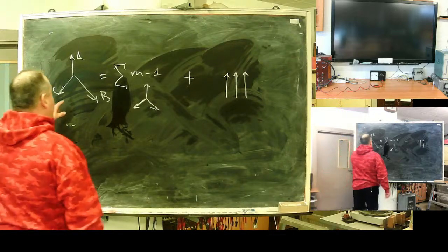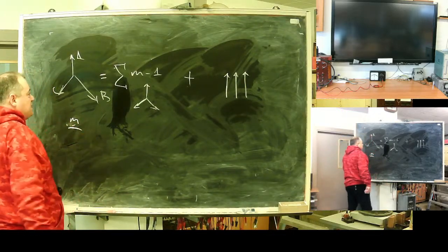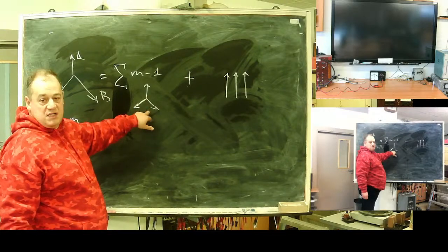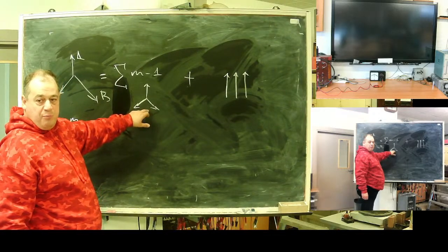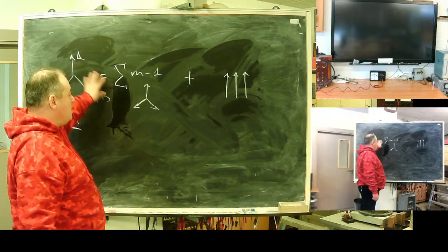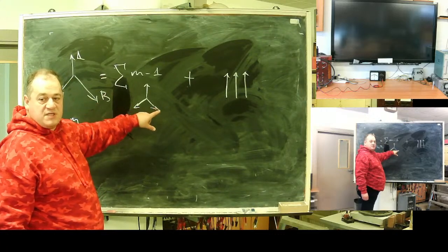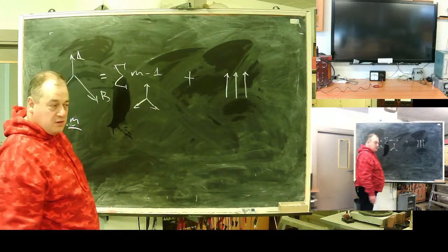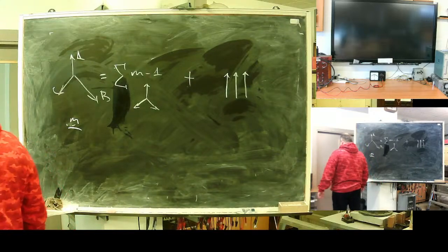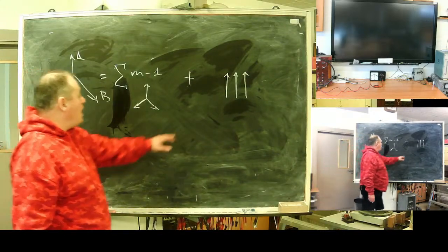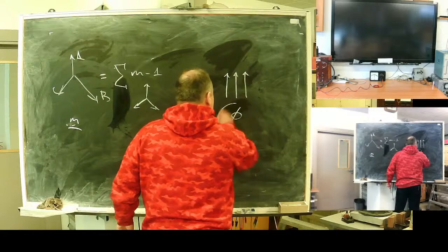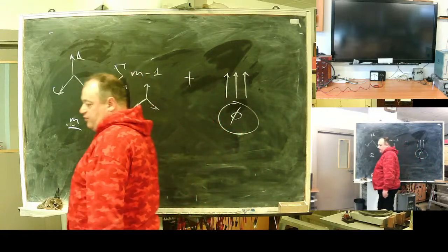If you have a polyphase system with m phases, there will be m-1 symmetrical polyphase systems with all possible vector sequences, plus one additional zero sequence system to reflect ground current.